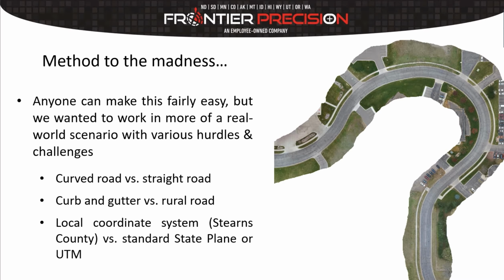And then probably the biggest one, which can be a pain when processing this data, is that we wanted to work in a local coordinate system. In Minnesota, where I'm located, every one of our counties has its own coordinate system. This was done in Stearns County. We wanted to work in that local projection, because that's what literally 99% of people in Minnesota work in, a county system.